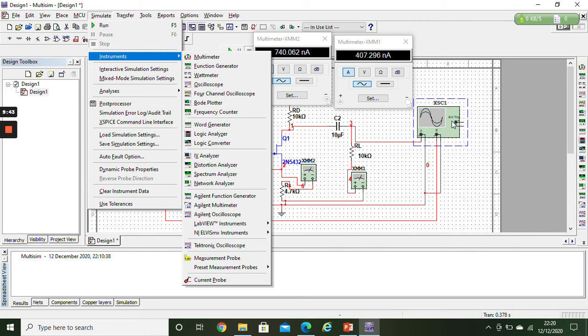And all you would be doing is noting the frequency, change your frequencies, right? I have just used a single frequency of 1000. You can change this, start from 500, then 600, 700, 800, 900 accordingly, right? Then you would be noting your input voltage, output voltage, and finally voltage gain, right? So the voltage gain values will come. You will be plotting those with your frequency.